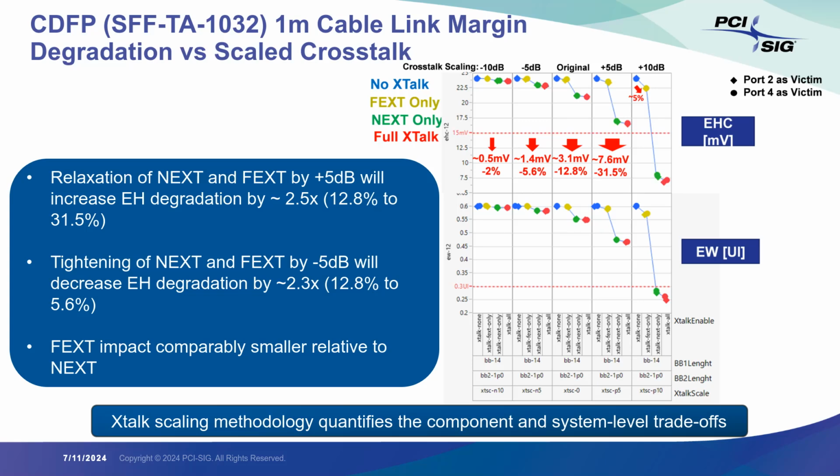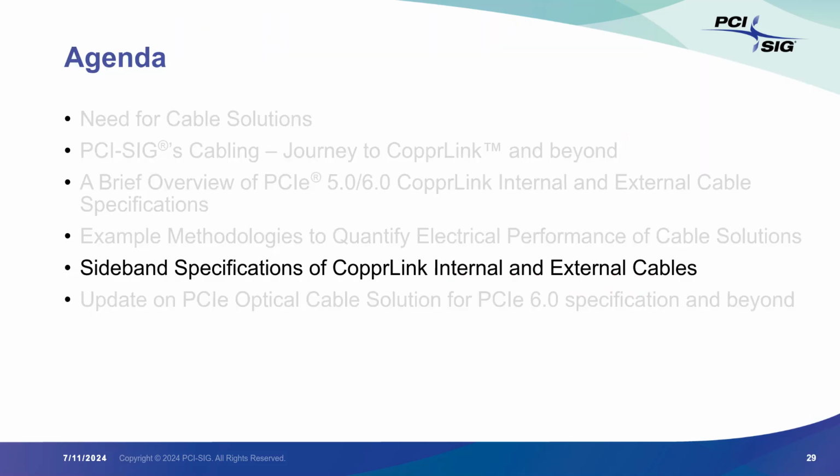So I'll hand over here to Sam to cover the sideband details of the specification. Thanks, Mohiuddin. Yeah, so we'll jump into the other aspect of these cable solutions apart from the high-speed interface: the control plane, or ways for the root complex to communicate and control endpoints on the other side of the link. PCIe applications aren't inherently peer-to-peer, so this control mechanism is extremely important in establishing a link and ultimately providing the flexibility for these cabling solutions to be adopted.